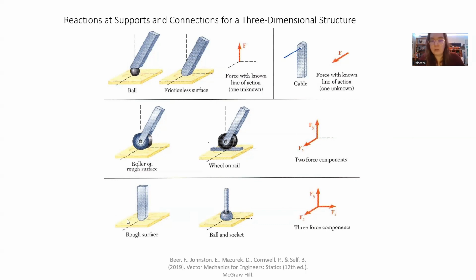When we look down to our rough surface and our ball socket, that is constraining motion in any translational way, any sliding way. It's not constraining our rotational moment. So we have a force in the X, Y, and Z axes, but we don't have any moments applied.